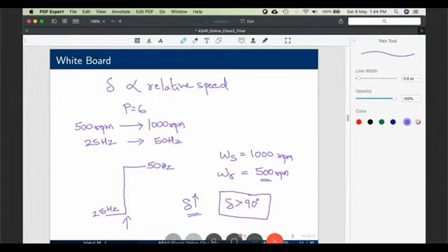So what is the workaround? Why did this problem come? We were changing frequency in a stepped manner. Say 500 RPM was here. We wanted to change it to 1000 RPM immediately. Instead, what we do is we gradually go like this. 1000 is here, 500 is here. Instead of a step manner, we give a delay, and after some time, we reach 1000.